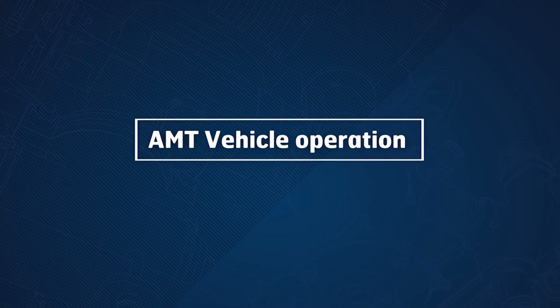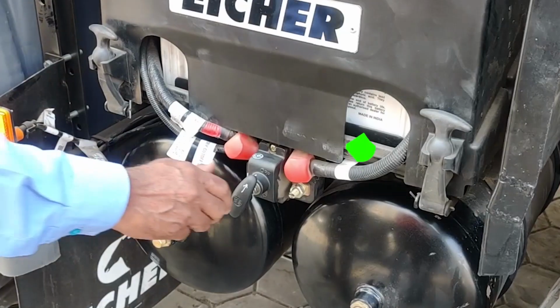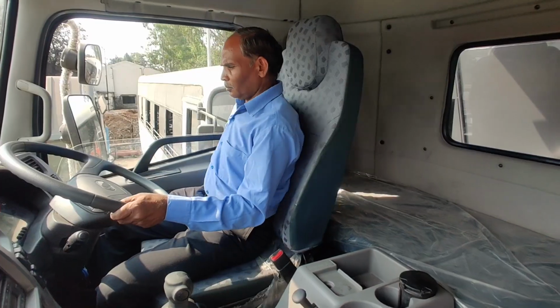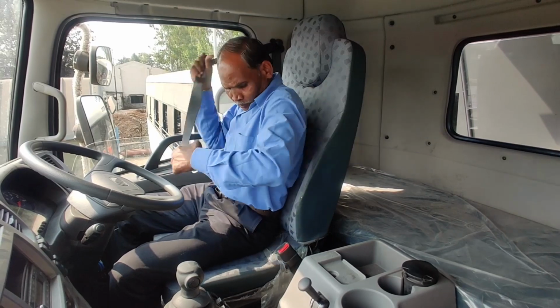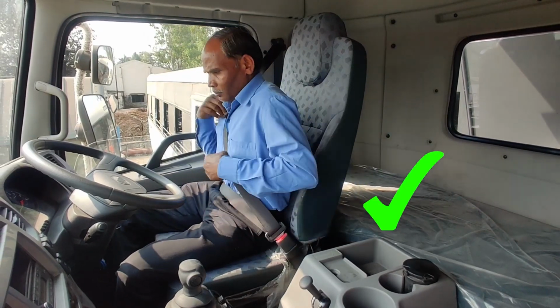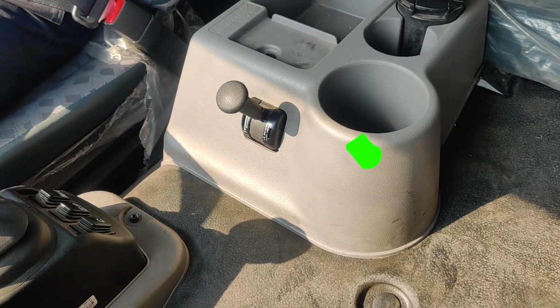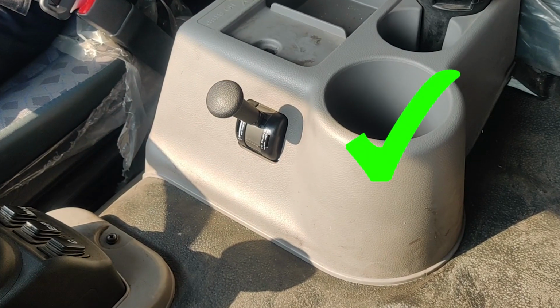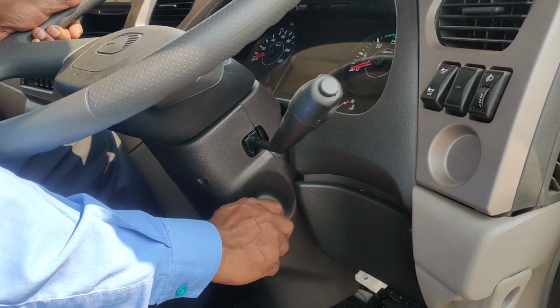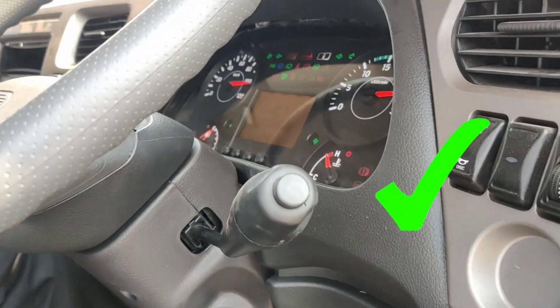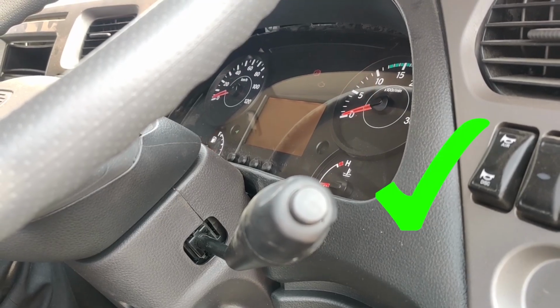AMT vehicle operation. Switch on the battery cutoff. It's important for drivers to wear their seatbelt to ensure safety. To start the vehicle, ensure the handbrake is in the on position. Turn the ignition switch to on and wait for telltale lamps self-calibration.